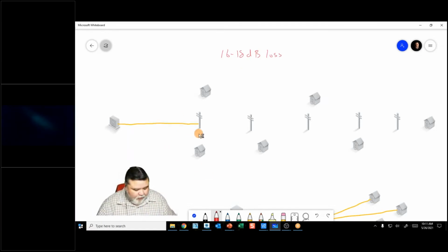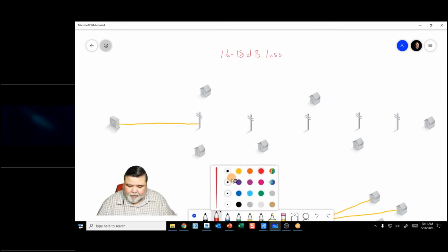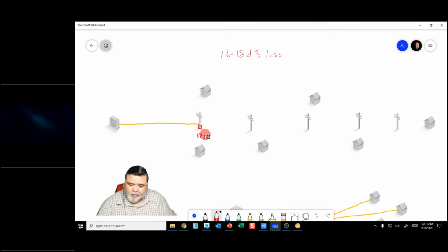So if I were to place this 1x32 splitter here, we'll do even money and say I would lose 17 dB in my power budget. Most fiber to the home systems are engineered around 25 to 30 dB, depending on the classifications. So now we're burning up a lot of our power. In an urban market, we're not running more than 1,500 feet to 5,000 feet or in that range of distance between the splitter and the subscriber, right?